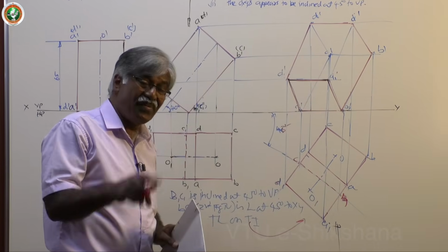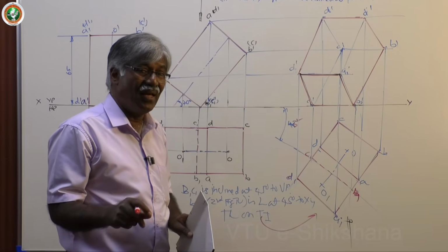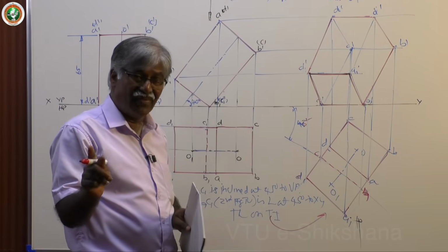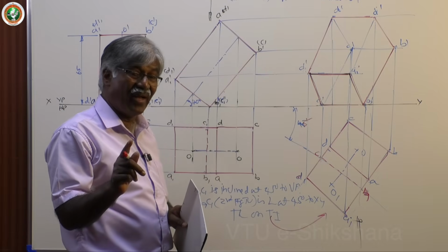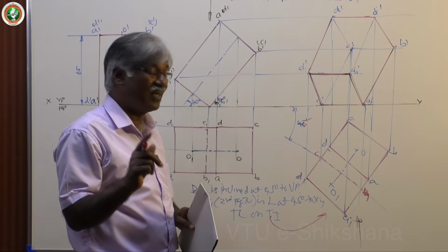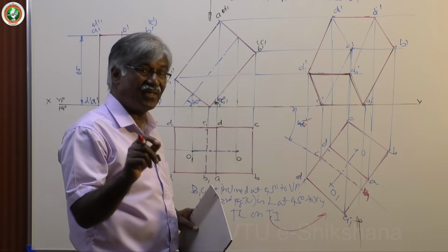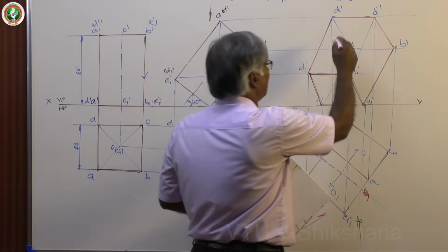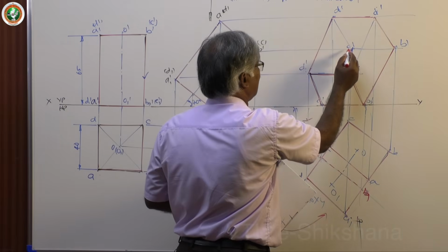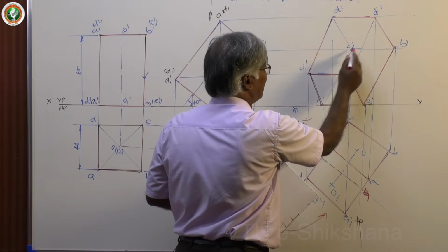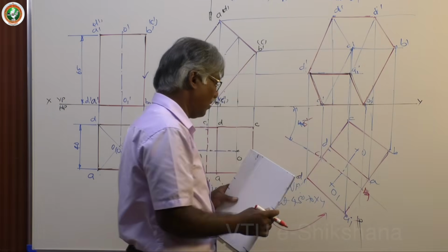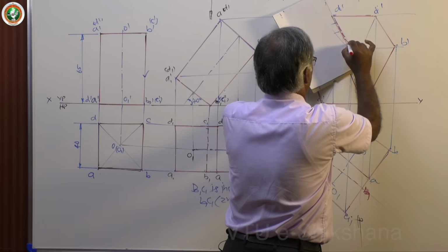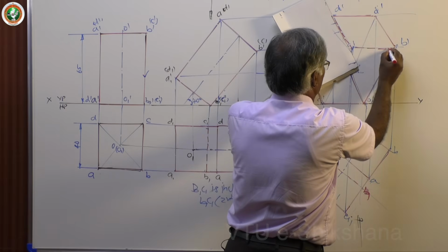Then the invisible key surface you take. All invisible key surface lines are dotted, that is invisible, but boundary lines always dark. You must have that condition in mind. Even in the farthest point method, we have taken that also. These two lines, C dash D dash, C dash B dash are dotted lines. So let me draw dotted lines or invisible lines for this. Okay.